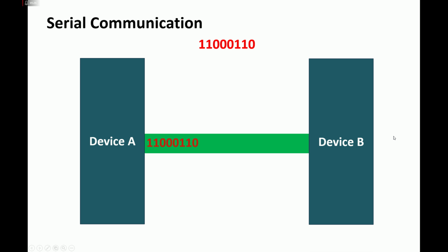Here the data will be sent one at a time, serially. So device A will send 0, 1, 1, 0, 0, 0, 1, 1, one by one. And if we go into it, the serial communication will look like this. See, we have this curve. Here this side is 0, then it became 1. It will look something like this, like we started our UART protocol at the falling edge. And you may set it to the rising edge as well, like by default it is at 1 or by default it is at 0. It doesn't matter. So in our case it starts from the falling edge.